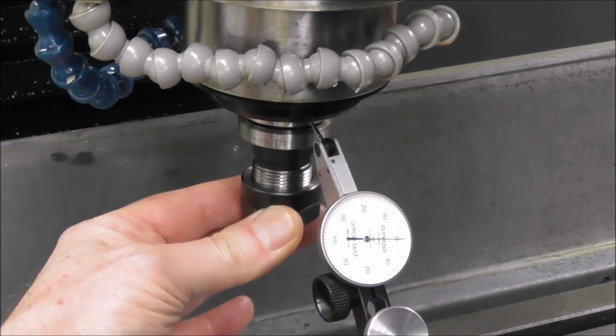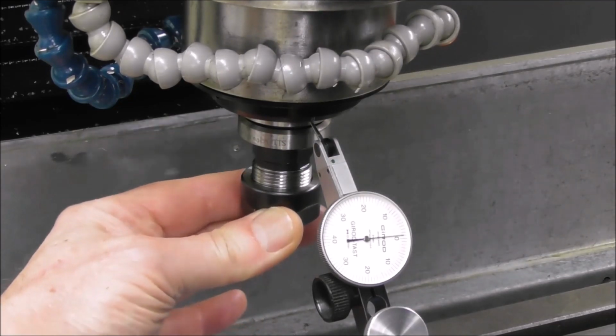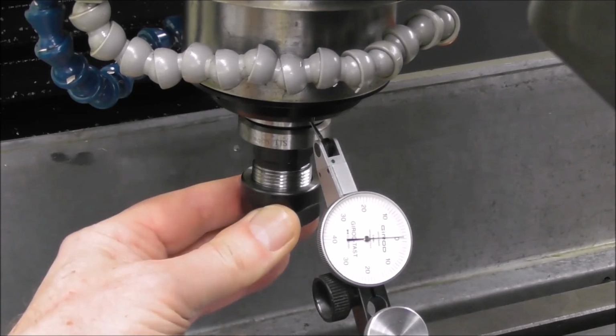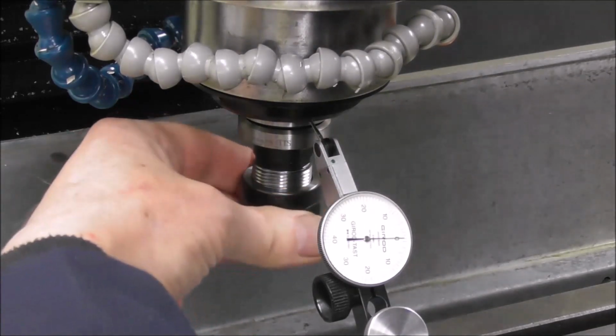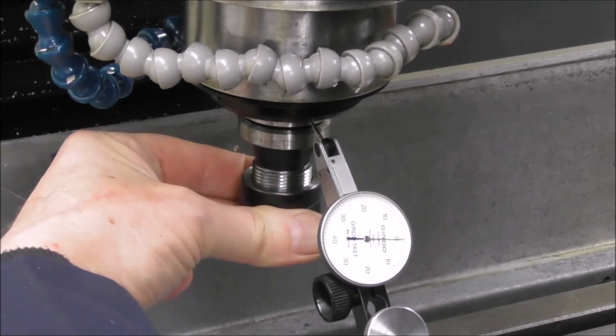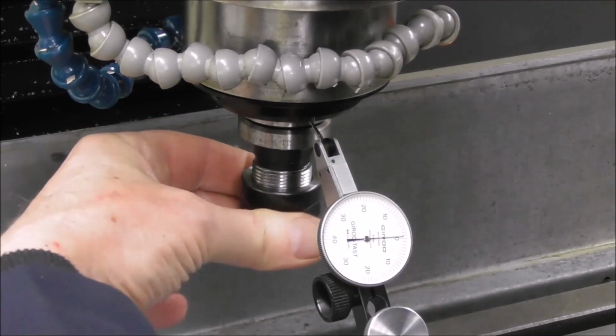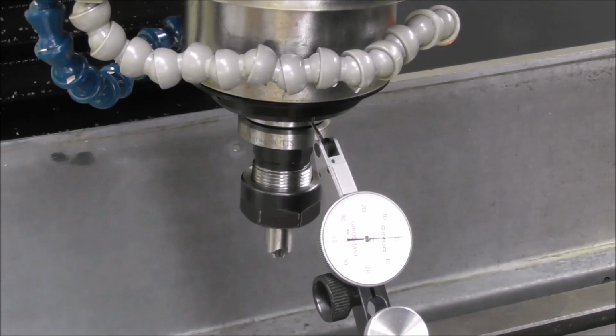I'll tighten it up now just on the spindle nose, and it's varying a little bit, but around about 1/100th of a millimeter, perhaps a bit less. So we're getting about 1/100th of a millimeter spindle compression and just over 1/100th of a millimeter TTS flange compression.